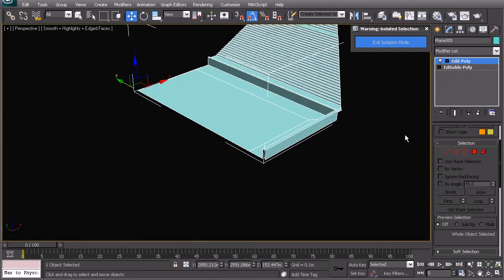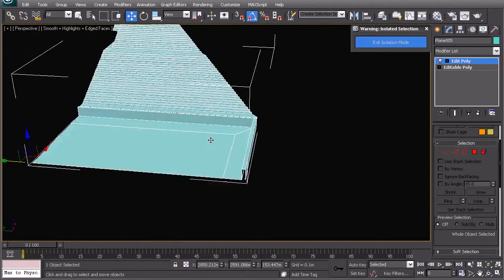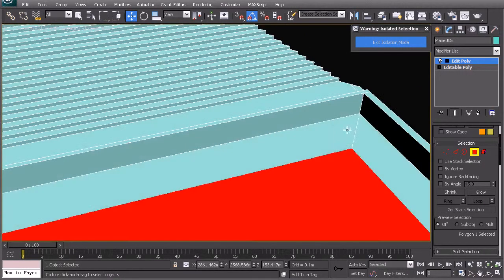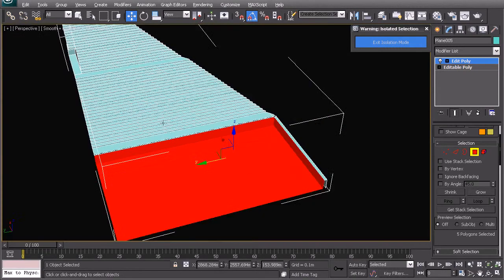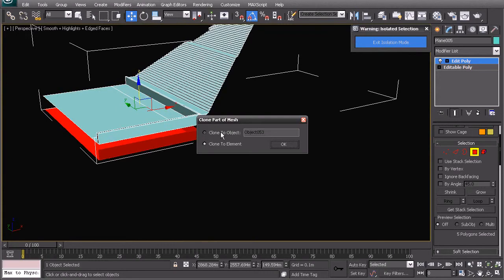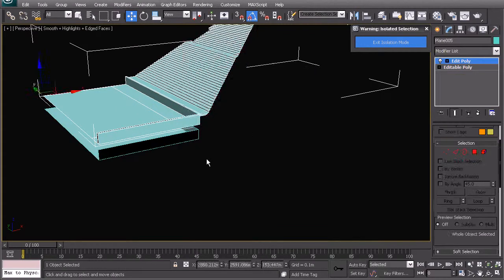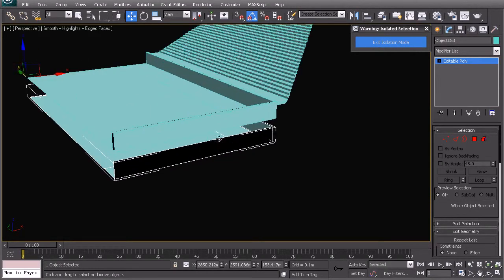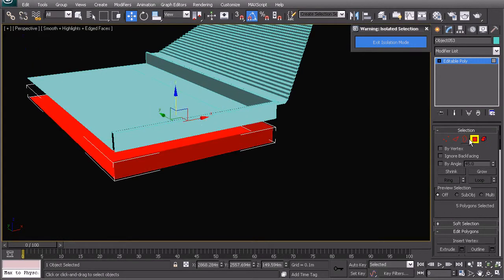So we're going to start by actually using some of the similar geometry that we've had on the stadium. In particular, I'm going to start with that shell. And I'm going to move that slightly down and just create a separate object by shift and dragging down. Since this object is facing outwards, I'm going to highlight all of the faces and just flip them.